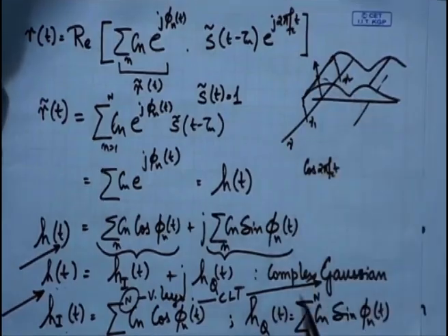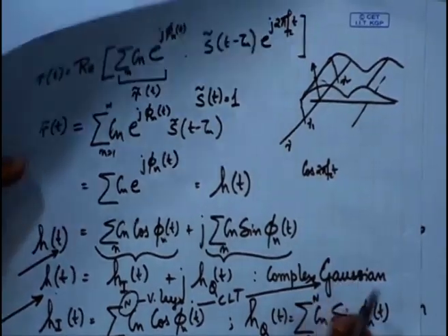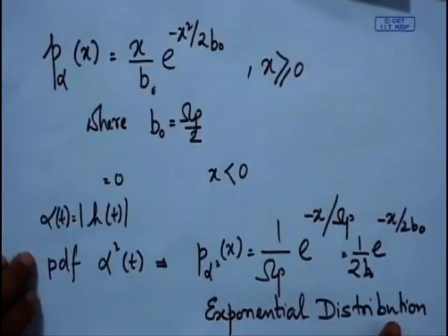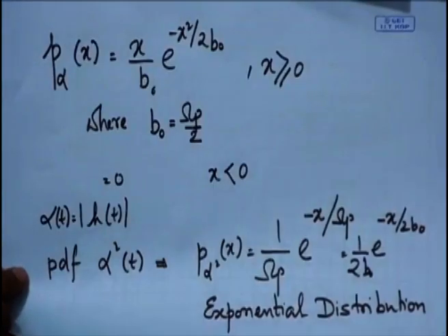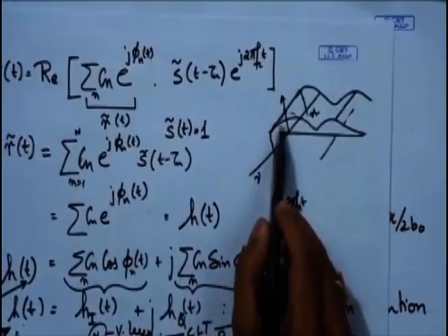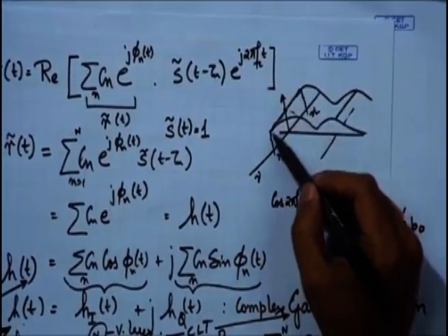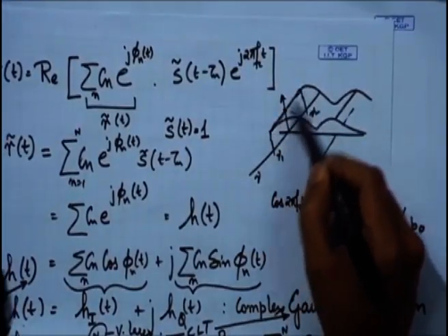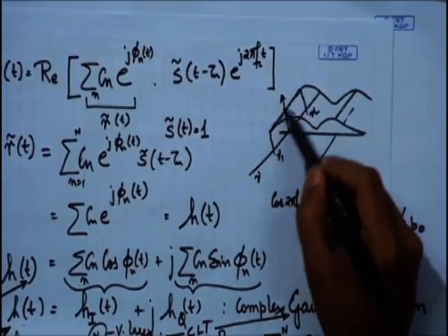Now, this is a very significant observation that we could make in our progress of wireless fading channels, and this time domain variation is resulting in the fade in time direction. In the frequency direction, it is frequency flat and not frequency selective.